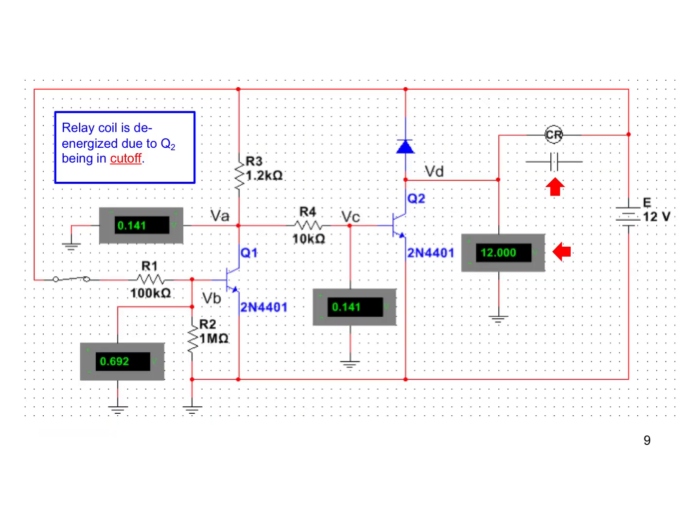Okay, again, here I just have the simulation, and you can see with that switch closed, this VB is the base to emitter junction. Just look where the meter is. That's typically your 0.7-ish. This is pulling VA down to ground, but it can't really be ground because of the saturation voltage. But again, I said if it's fully saturated, it's in the 0.1 to 0.3, and it's right in that range.